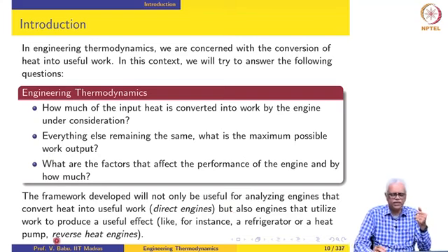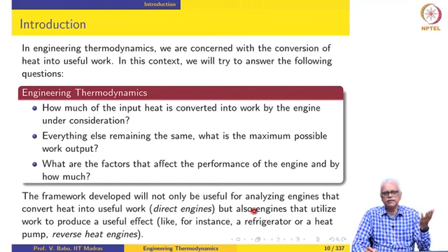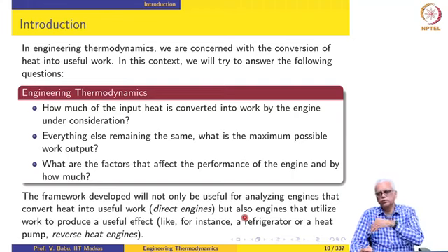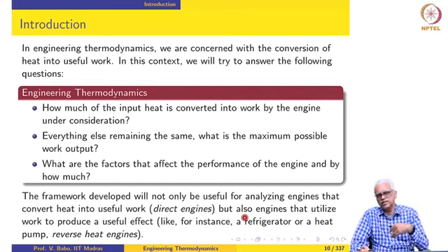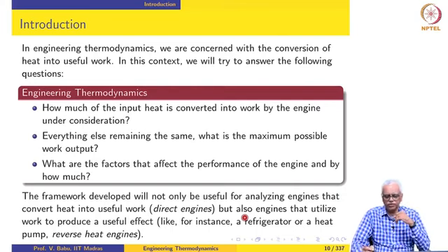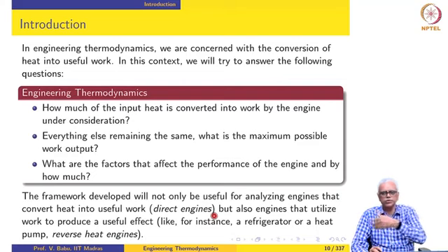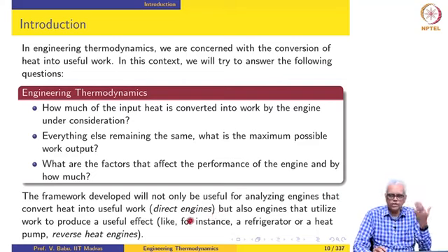Heat pump on the other hand, which is used widely in western countries, particularly colder countries, is used during winter time to pump heat from the outside ambient, which is at a low temperature, into a dwelling or a house and maintain it at a comfortable temperature. So, we actually pump the heat from the cold ambient into the house which is at a higher temperature and maintain it at that higher temperature. So, that is also a reverse heat engine which absorbs the work. As you know, normally heat will not flow from the outside ambient which is at a colder temperature to a house which is at a higher temperature. So, this has to be accomplished by supplying power or energy to a device.